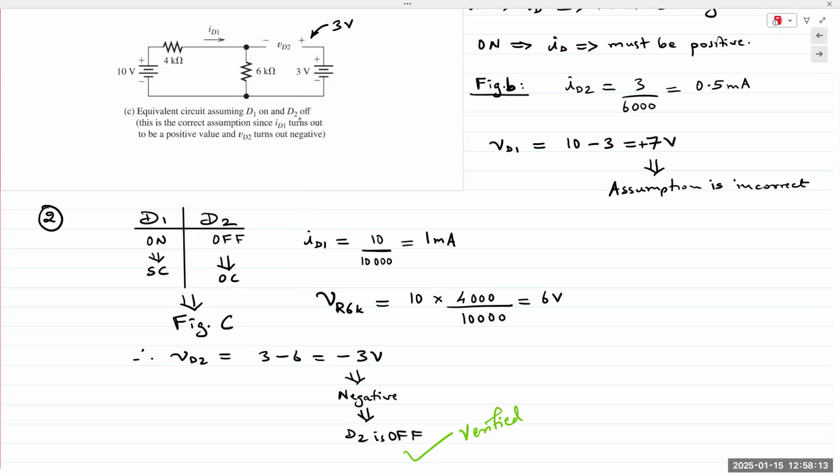Yes. So if I understand you correctly, the question being asked is, we have two diodes, we made two assumptions, right? We made one assumption for D1, one for D2. One was correct, the other one was incorrect. Can we keep the correct portion of it? The answer is no, right? Did I understand it correctly? Yeah. So we can't. The assumption is basically for both D1 and D2.